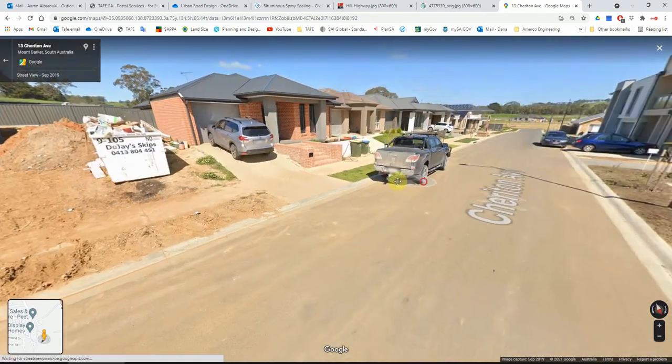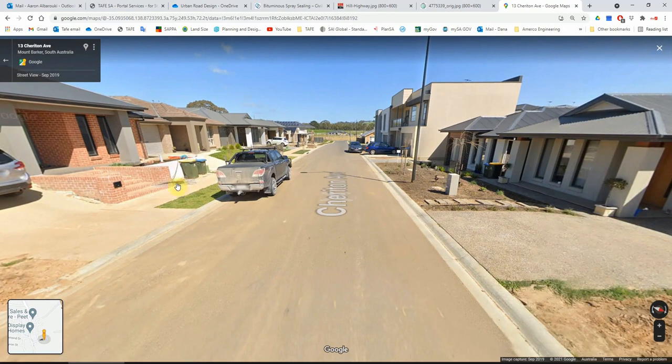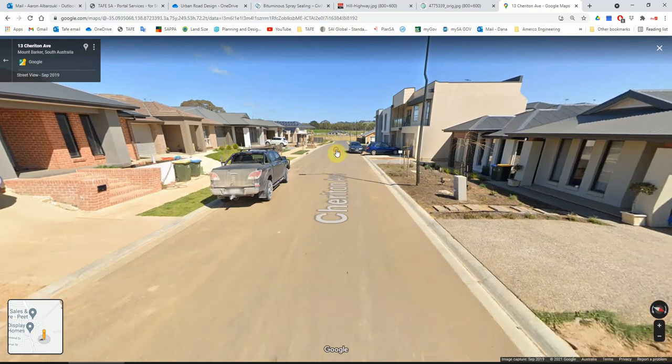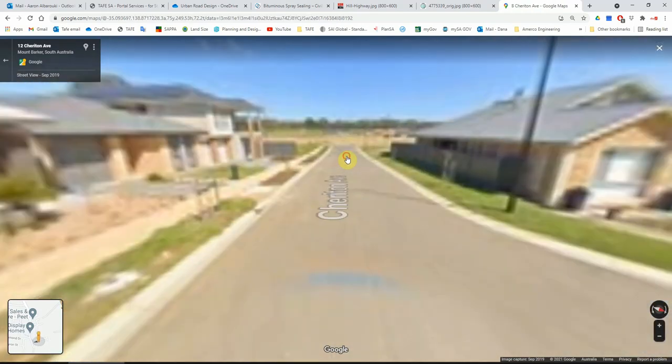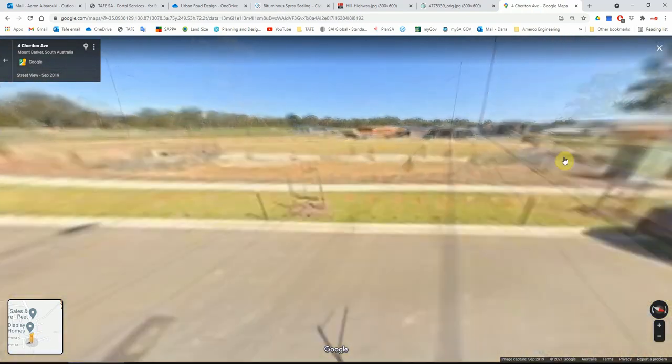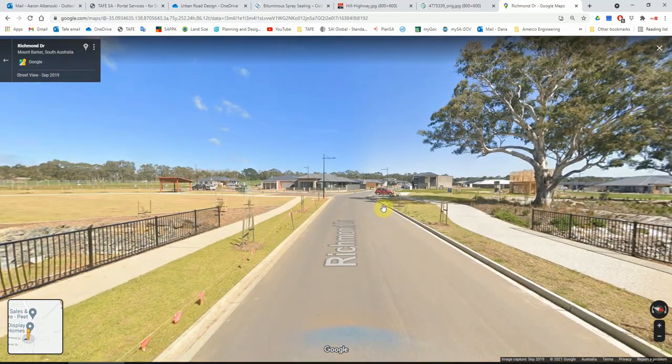And usually, as you can tell from all the examples that you can see here, the houses will be built around this area. It will be slightly higher off the road. In other words, the road will be slightly lower than the existing surface, which will be making the pads for the proposed houses or the new houses. So if we have a quick look at these examples in different areas, as you can see, the road is slightly lower than the surrounding grounds. This is the main rule that we have about the profile, and this is what we should be creating there.